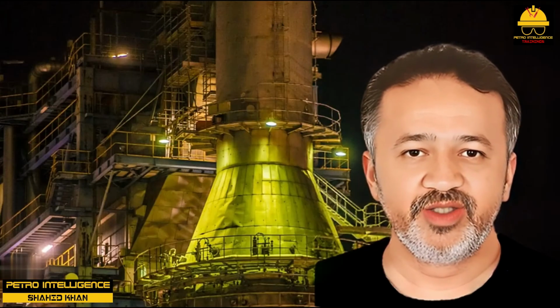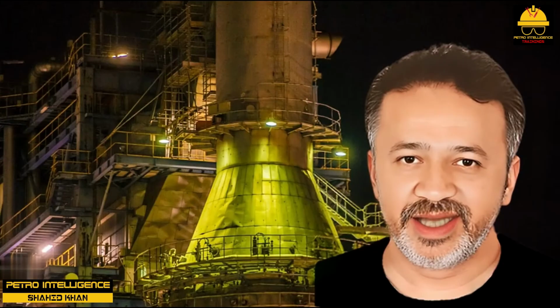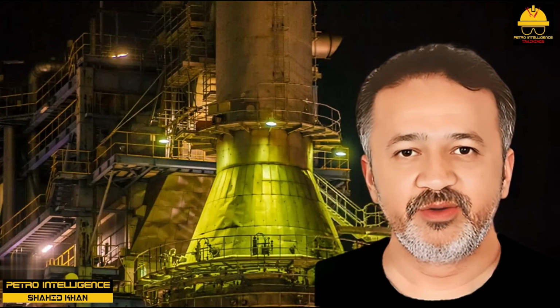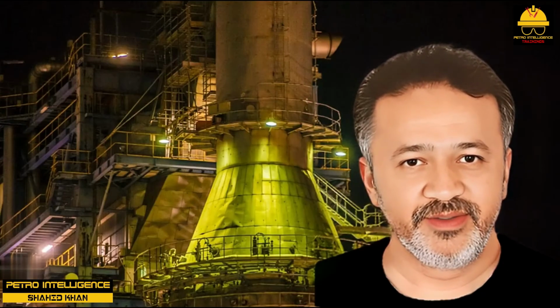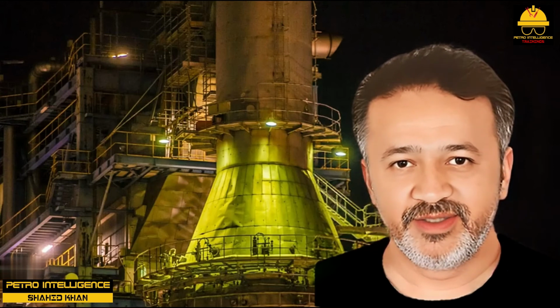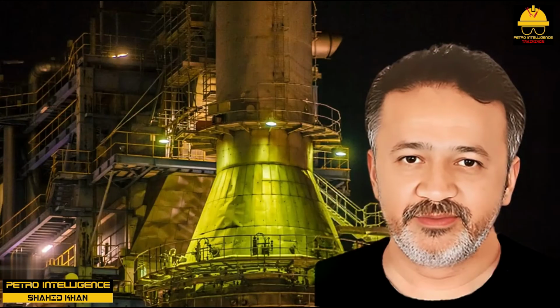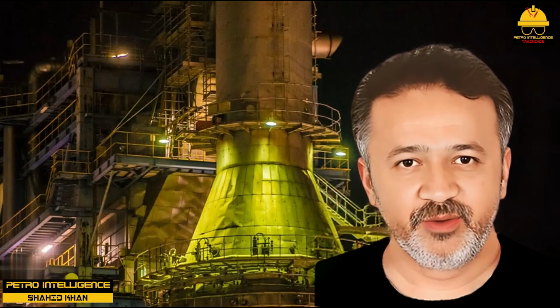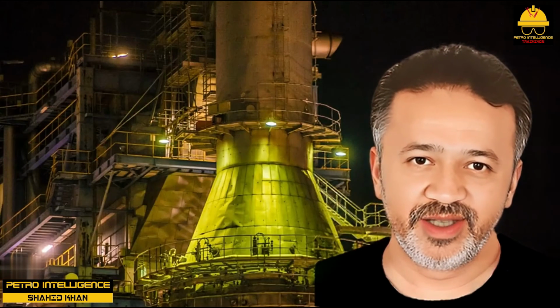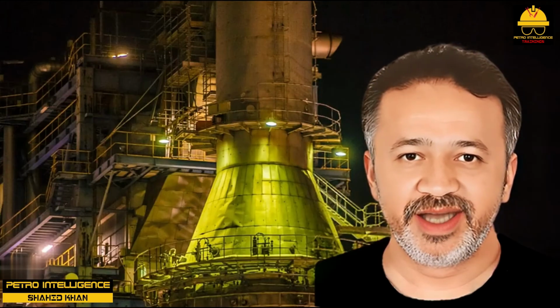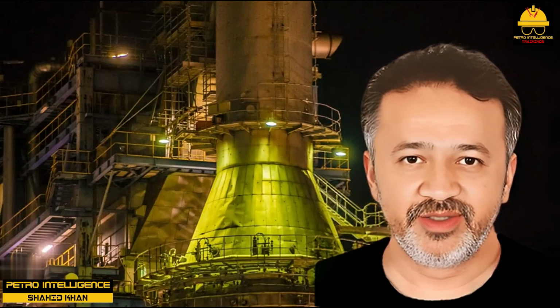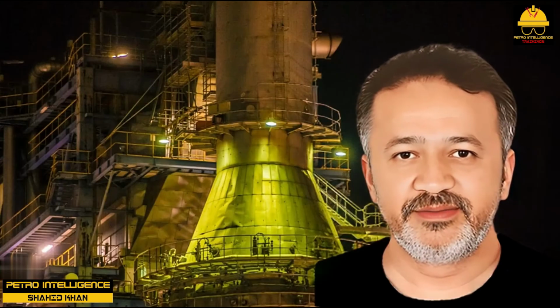Suppose we put the air registers back as they were and pinch on the stack damper instead. So, let's suppose we restrict airflow via the stack damper until the firebox oxygen goes down from our base case value of 6 to 3%. The oxygen in the convective section will also be reduced to, say, 5%. In this case, we see that the delta O2 is also much less, only 2%.